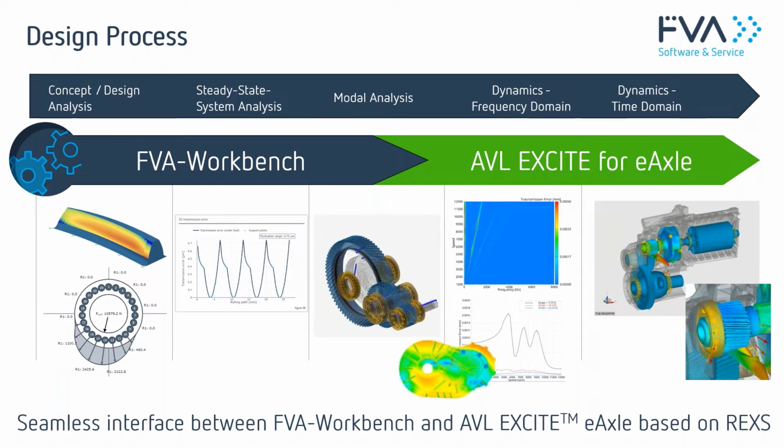So we can provide the bearing lifetimes, the bearing loads, and the safeties for the tooth lengths and for the shafts. And we can also calculate very exactly the frequencies which are excited in the gear meshes. So we have the exciting frequencies, and we can calculate the eigenfrequencies in the drivetrain because we have all the stiffnesses and all the masses available within the workbench.